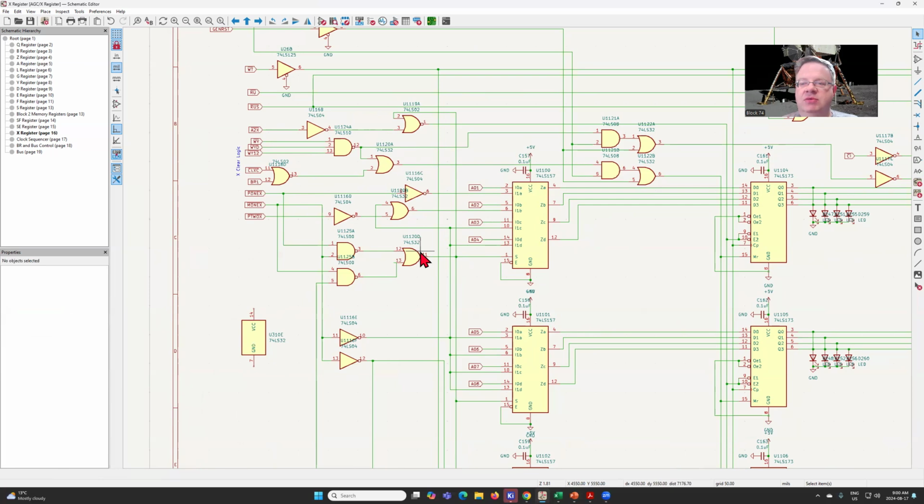So two things happen. One is we want to generate our enable pulse so that we can load that data into the actual X register. This is our 74LS173 4-bit D registers that will actually store the data. We have our logic up here where we combine it with the A2X pulse as one option. And then we also NOR that with logic that comes from whether we have one of these asserted: the P1X, -1X, P2X, or B15. If either of those scenarios occur, we're going to use that to enable our write-in.